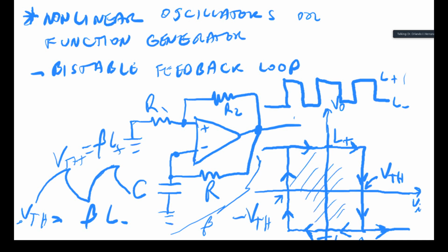So now you have an oscillator, very simple oscillator based on a bistable loop. This is also used in integrated circuits because of its simplicity. Like I said, it doesn't require a great op amp, because all it has to do is switch, and you can build that easily with like 9 transistors, and then it just requires 3 resistors and a capacitor. And if you don't want to use your microcontroller's crystal and use the built-in RC oscillator, that's what they have inside the chip. Okay, very inexpensive.